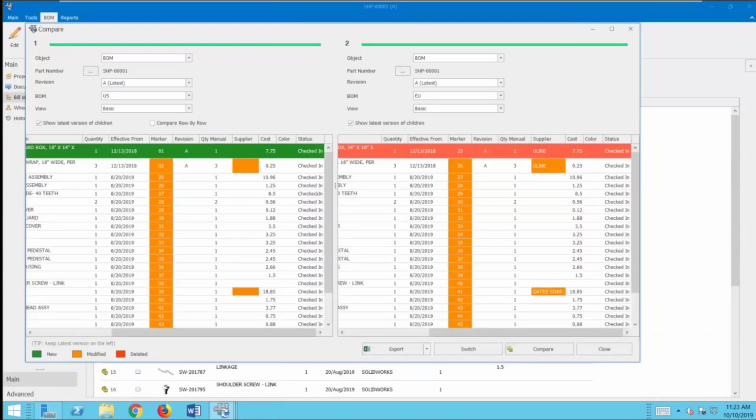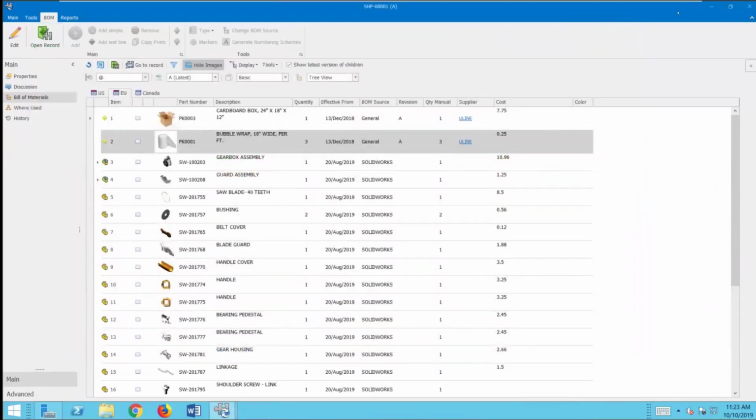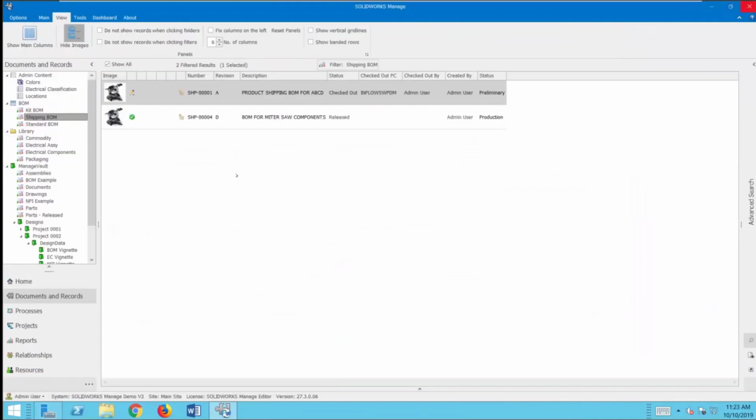The last thing I want to show here, we're going to do a quick import for a bill of material and try to save some time for some questions here as well. Save this and close this. What I want to do here is we're going to take a quick minute. What we're going to do is we're going to take an Excel sheet that's been formatted, and we're going to bring it in to complete a bill of material for a part that's purchased. So we want to have some records of the parts that are inside of what we're purchasing for further down the line. So we're going to take an Excel sheet that's formatted and bring it in to one of our kits, our electrical assembly, sorry.